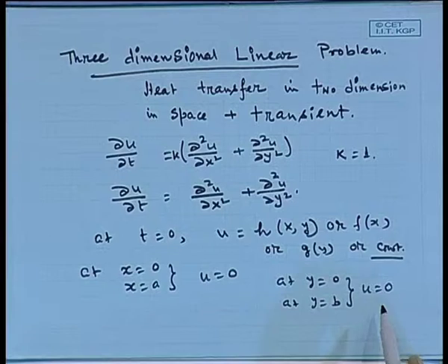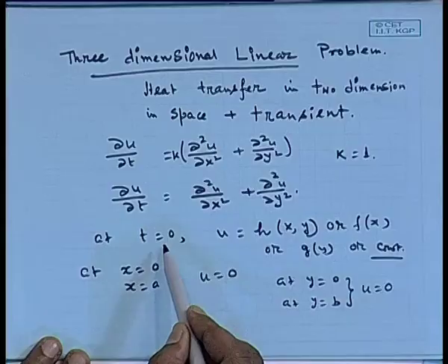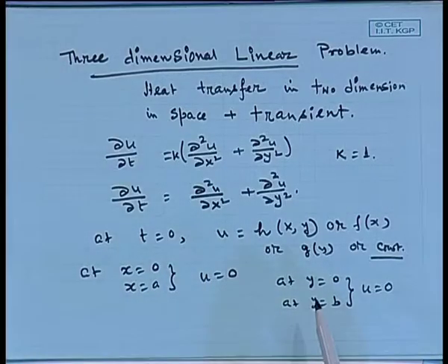As I told earlier, in a general problem, you cannot have such well-defined boundary conditions. You may have various temperatures, let us say T1, T2, T3, T4. These will give you non-homogeneous equations, and we have seen in detail previously how non-homogeneous problems can be tackled by splitting them into sub-problems, and so on. So, I am not considering all those problems in detail, I am just solving a base case. This is basically the base case, right. You have one non-homogeneous initial condition and all other boundary conditions are homogeneous.